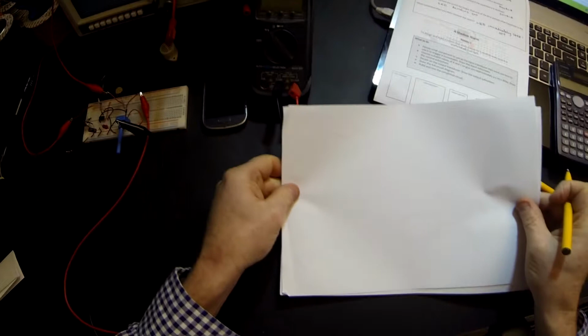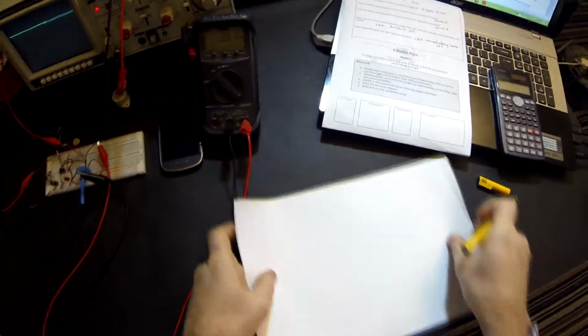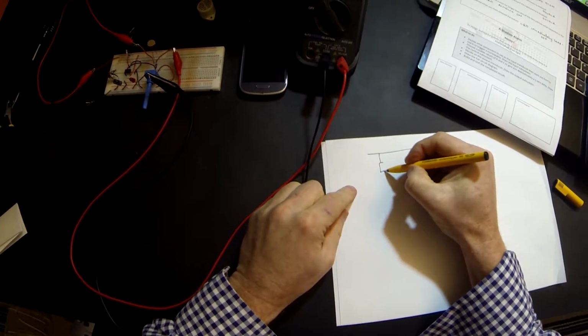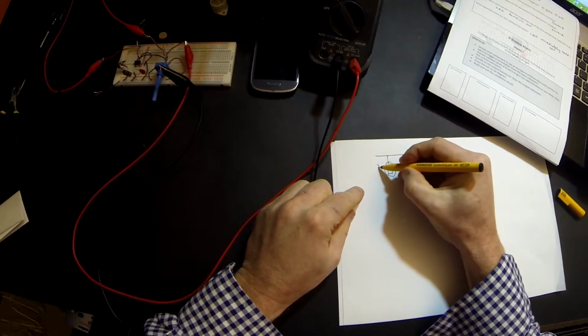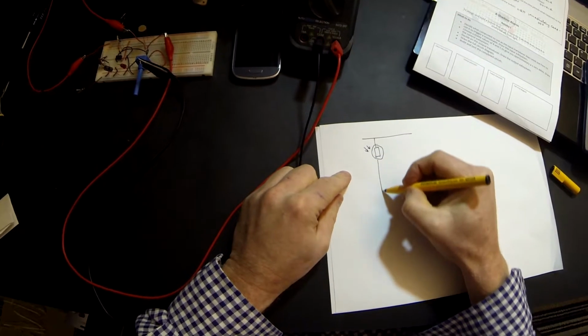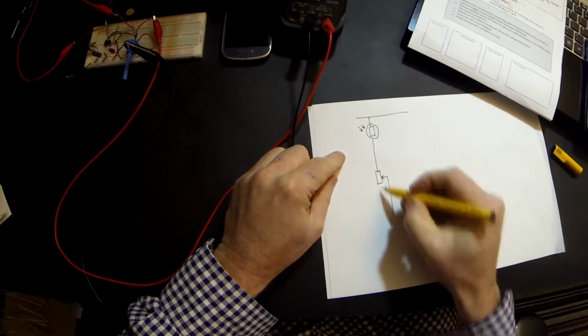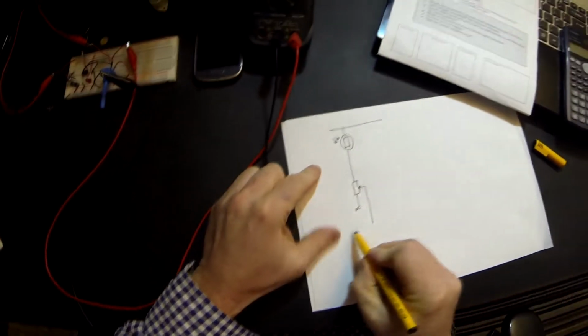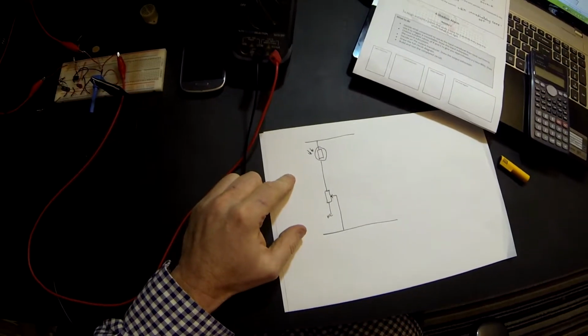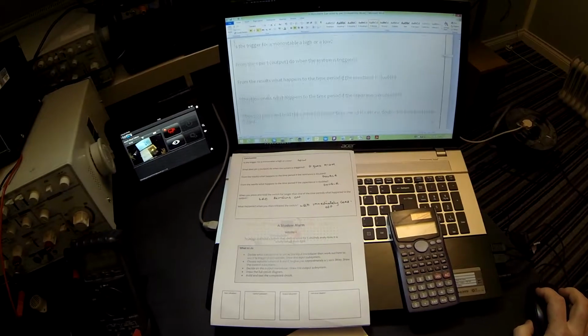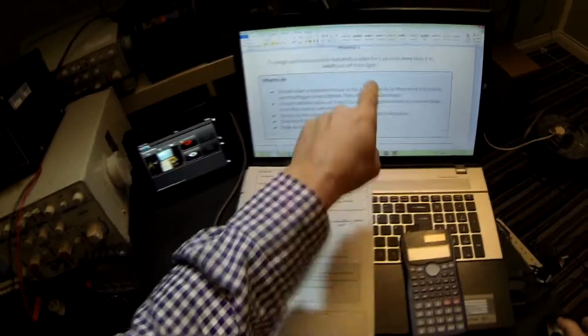So the first part of our circuit can be a LDR with a variable resistor, no connection on the third leg, like so. Next, we need to work out our monostable time for a 5-second delay.